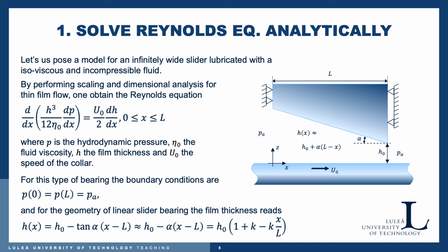And you can think of this problem now as we have flipped the real thrust bearing upside down. So the collar sits beneath and the pad is the inclined surface here, the top surface here. In a real thrust bearing, in a hydropower plant, these two change place and the collar is on top of the pads.